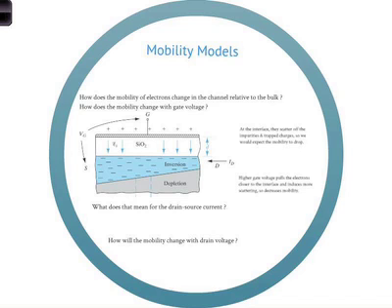What does that mean to the current? If the electrons are moving more quickly, the current should increase. You have more electrons going by. Yeah, so of course, if I plot current as a function of the field, current is increasing, but at some point it should saturate. Yes, it will saturate. So the current saturates with respect to the drain. Think about that for a second. What is the other situation when that happens, which we just talked about? Just now, in the MOSFET.